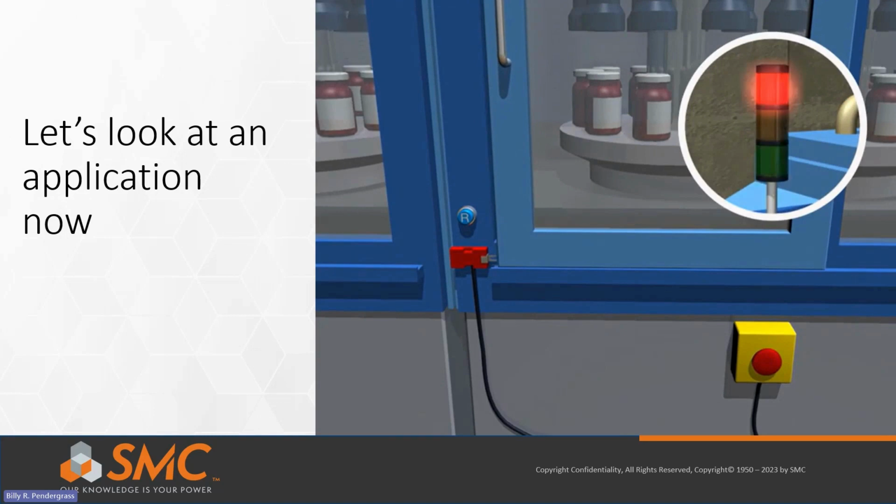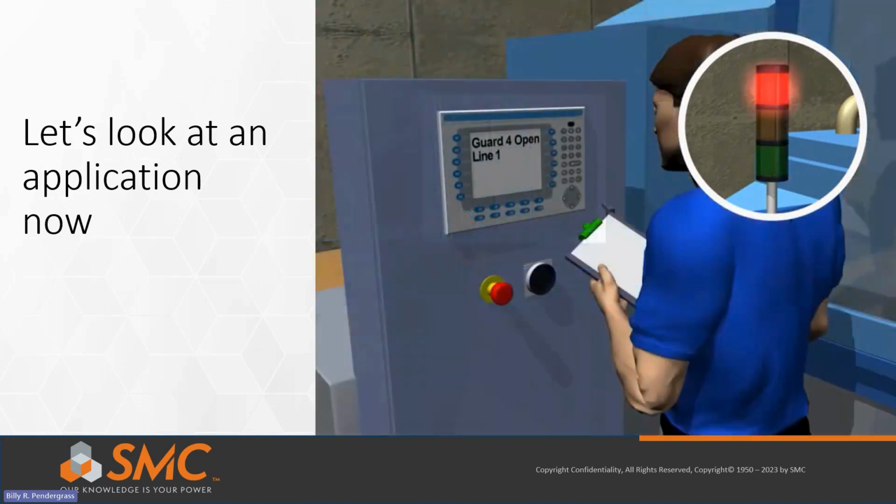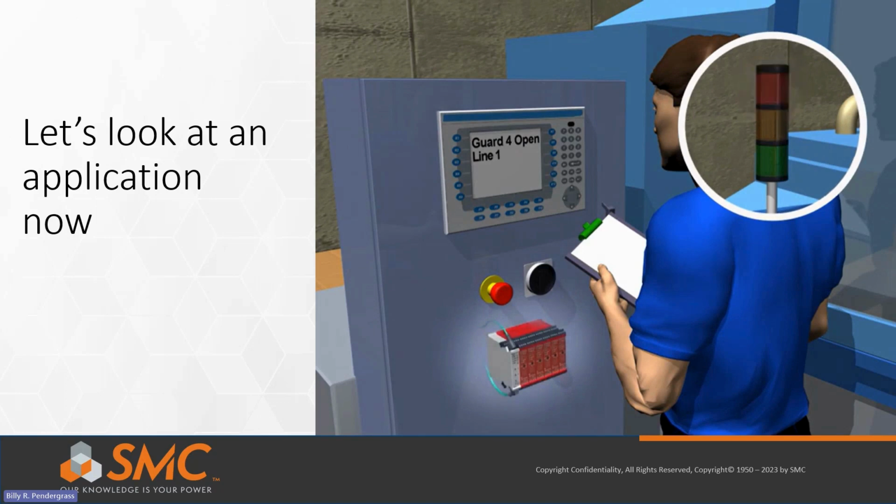If an e-stop or an interlock switch is operated, that individual safety signal will be sent to the Guardmaster safety relays. The relays are optically linked to each other, requiring no wiring for communication between them.